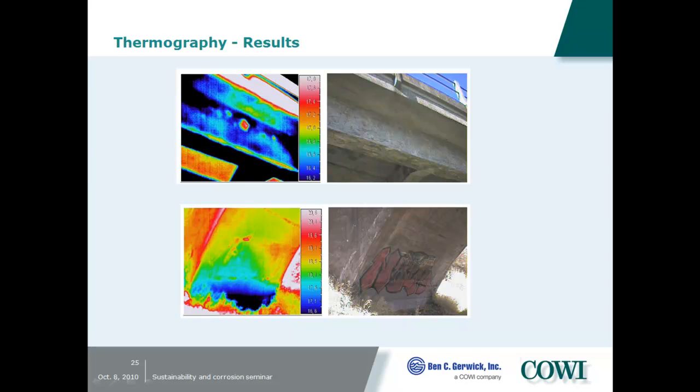You should use this method at times where there's a change in temperature. That means early morning, late evening. And then you can detect smaller or large areas where you have a significant change in temperature in your structure, and you can then evaluate that it could be a potentially delaminated area. We normally record both the thermography picture, that's what the camera does, together with what it looks like in real life. So do you typically use this before you go with the hammer? On some structures you cannot go with a hammer unless you have a lot of scaffolding, so it's a combined thing. Yeah.